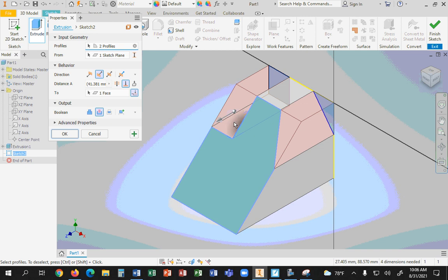If I change the dimension of the object, or if I change the angle of my cut, of my wedge, let's say the customer comes back and says, oh, I want a different angle, I want a specific angle. Get it? This cut will just keep going with it. No worries at all. That's the para side of parametric. It works with it. That's why I'm suggesting you pick face.